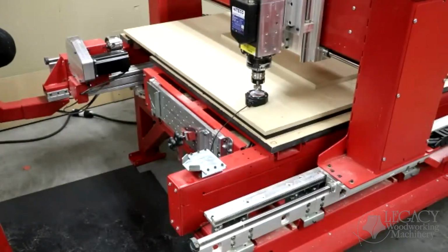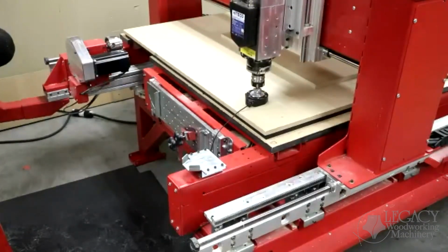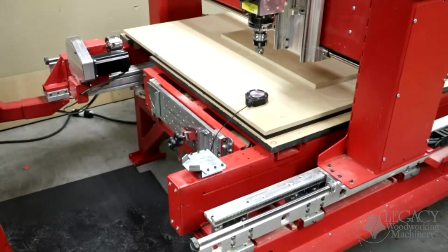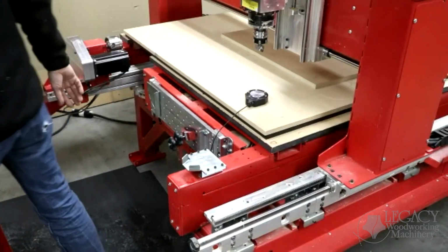Okay, and we're real close. This is going to go fast. I'm clicking on the single tool button right now. Okay, so it just set the Z0 1 inch below the top of that pad because we told it the pad was exactly 1 inch thick, and we know it's thicker than that, so we're safe. Now it also turned the smart tool off.